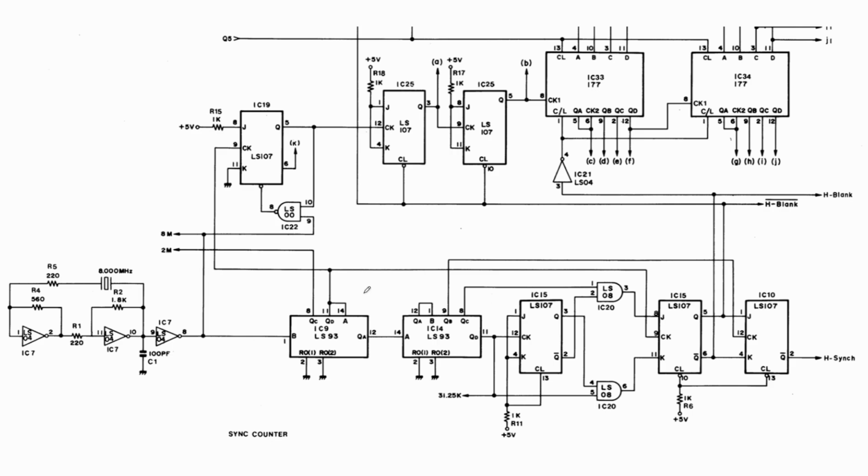Another quick intermezzo to explain this. This is the oscillator, the 8 megahertz oscillator. Through a divider, this becomes the 2 megahertz. It goes this way. It becomes the 2 megahertz that feed the CPU. But in addition to coming here, and it's going there, as you saw, I just checked continuity of this line, and it is going there. But it's supposed to also go to the shift register this way. This 8 megahertz signal is the one that's not getting to the shift register. And it also goes here to pin 9 of IC22. It's supposed to go there, but it's not going.